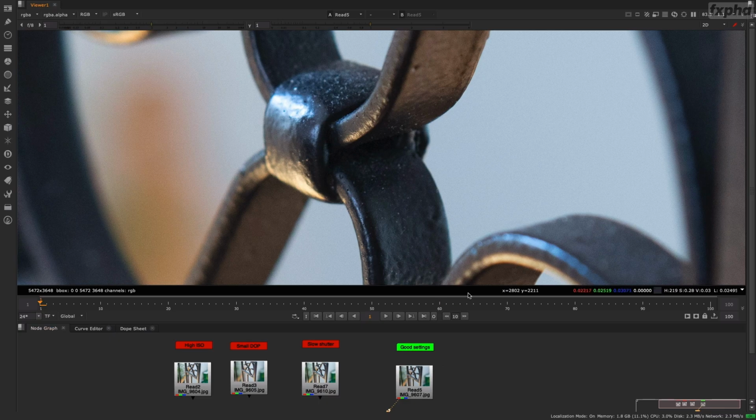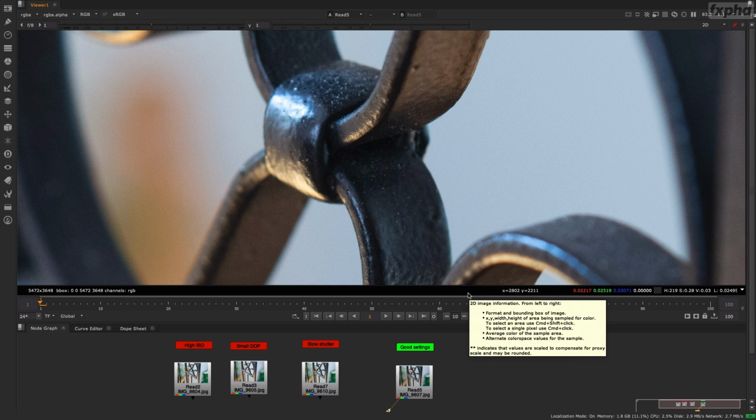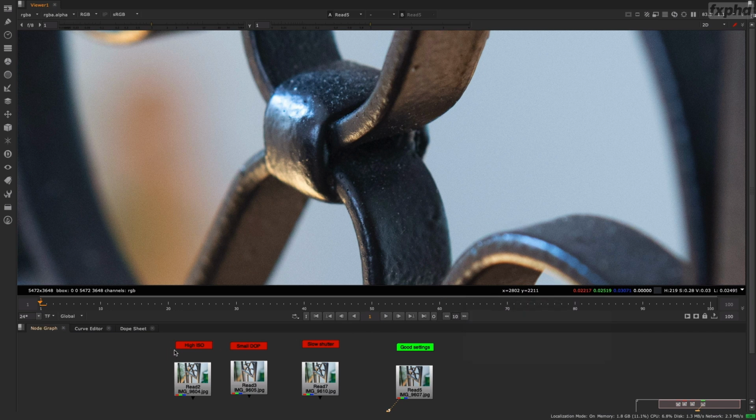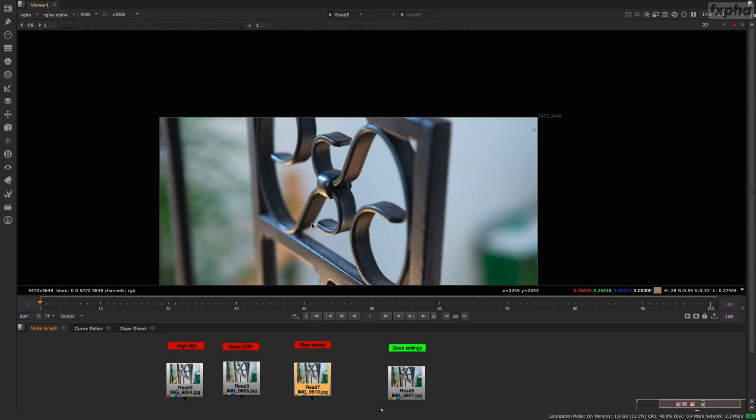And also a tripod, when you have a low light situation, will allow you to have the optimal setting for your lens. So you'll be able to use a low ISO setting with a closed lens so that you have a sharper image, and also will make sure that your camera is not moving, so you'll be able to use all the best settings for your camera. So that's something to take into consideration when doing photogrammetry. Make sure that you're giving the software the best chance possible to solve the best image possible.